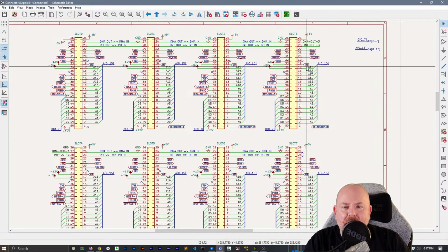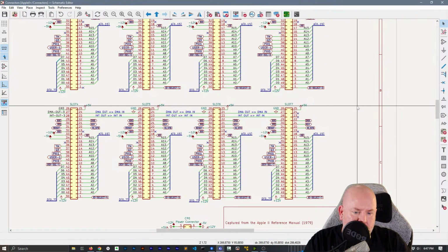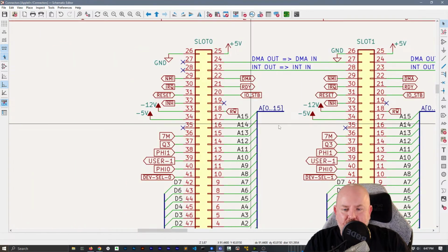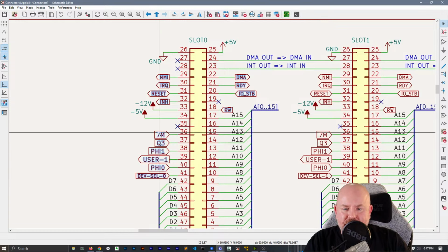I must have highlighted one of the wire connections or more. Wrong chip. All right, tell you what, let's just do this one block at a time, and it'll be easier to notice my mistakes. Change to hierarchical label.